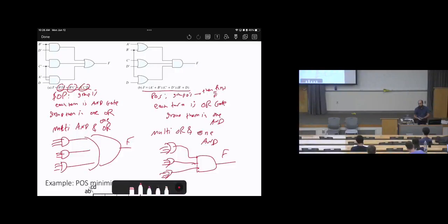Okay. In summary, we know how to do Karnaugh maps. Karnaugh maps can be divided into two ways. The normal way that we used to do, which is the sum of products: basically, we group the ones and get the function. Product of sums: you group the zeros. After grouping the zeros, you will get the function F bar. This is not F, this is F bar because we are grouping the zeros. Then find the complement using De Morgan's theorem to get the function. Then it will be products of sums instead of sum of products. That's how we deal with it. So in case you see any of this in the exams, you should be aware how to deal with all of these.